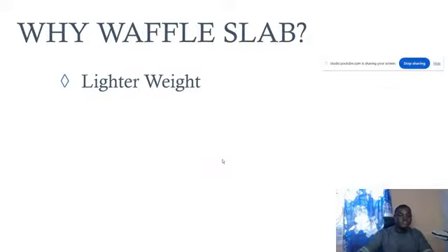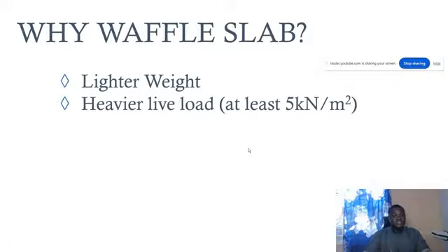Then another reason why waffle slab can be considered is that it is suitable to support heavier loads. Waffle slab is technically provided where we have longer spans and the live load we need to take in that kind of situation is high or heavy. From theory, they will tell you at least 5 kilonewton per meter square.